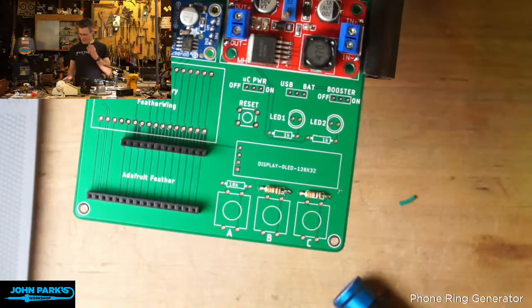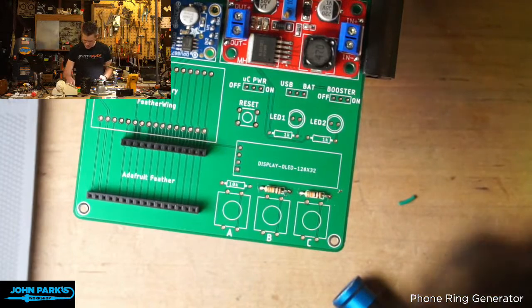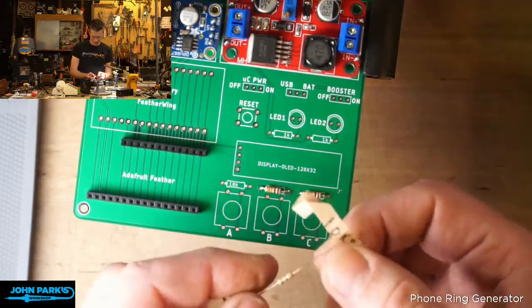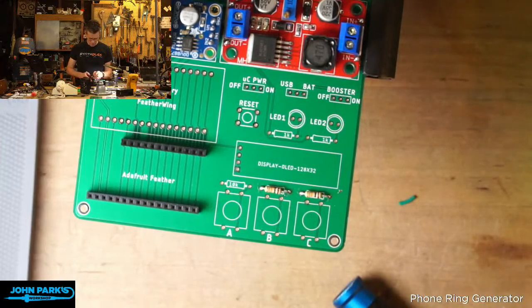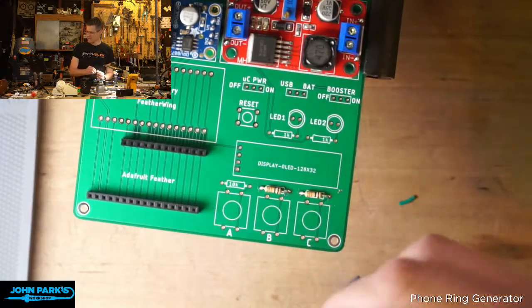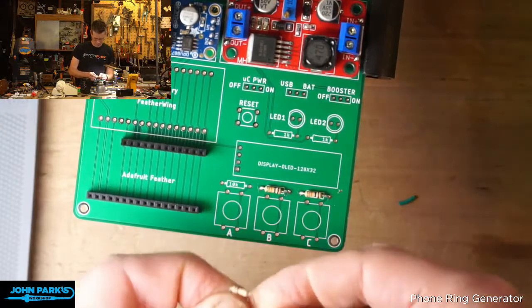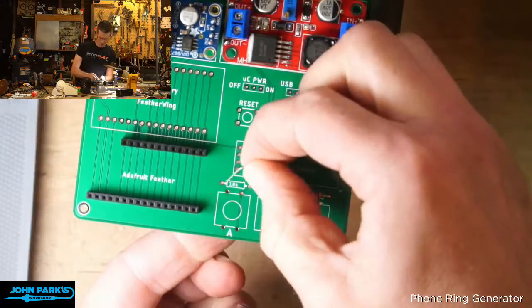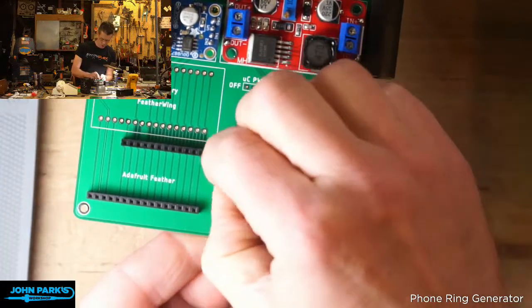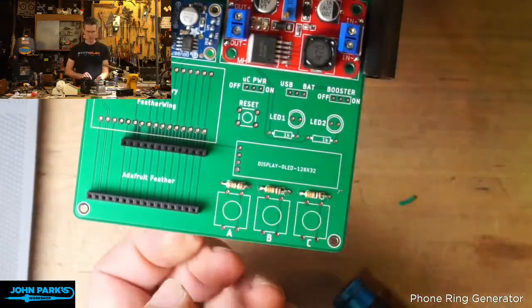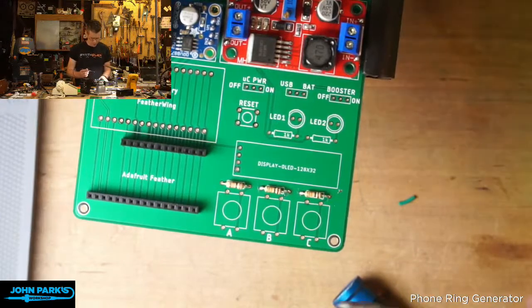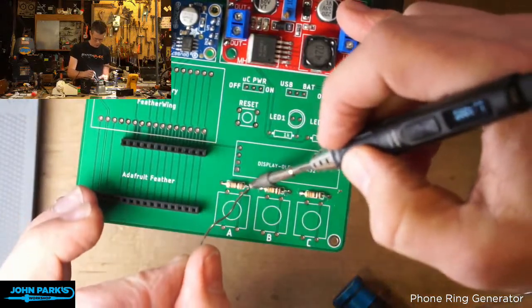Tolerance bands on the left or right, OCD question. C. Grover says: I've done them wrong. I prefer to put them on the right, I put them on the left, but I'm at least going to keep them self-same, consistent. Good question. What C. Grover is referring to is the color bands on the resistor that tell you its value and its tolerance. Since I tend to read that, and a lot of people tend to read that, left to right, if you're really particular, you'll want to put them in the same direction. It makes them easier to look at and know, oh yeah, those 3 are all the same. So I have the gold band, which is the tolerance, which is what, 10%? I think that means it's within 10% of the color code, so 10% of 10K in this case.